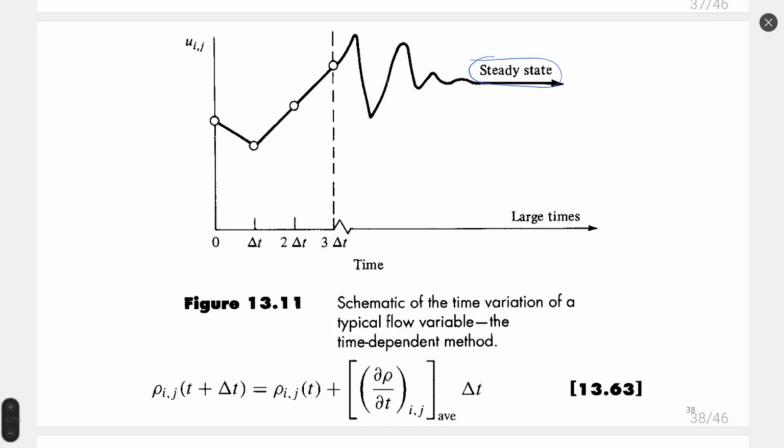Velocity can increase, can decrease, but if the process converges to steady state, it will be a constant value for each point. We can observe this behavior for all points in space. Each point has its own convergence process, right? What we see in residuals in ANSYS Fluent is the maximum value of this time derivative behavior among all possible points in space.